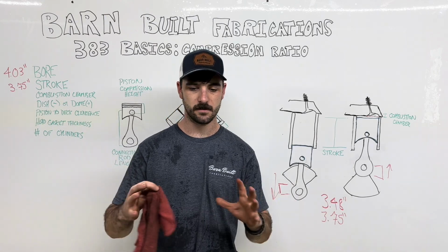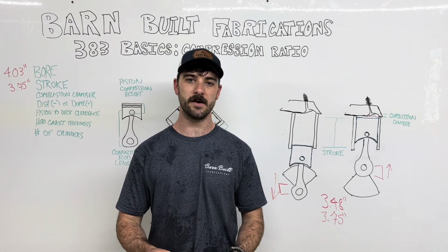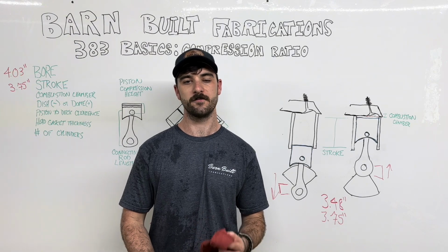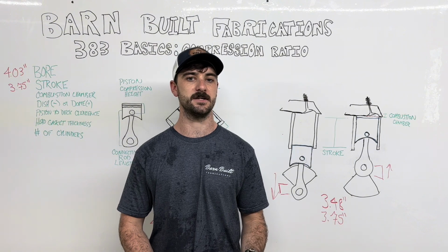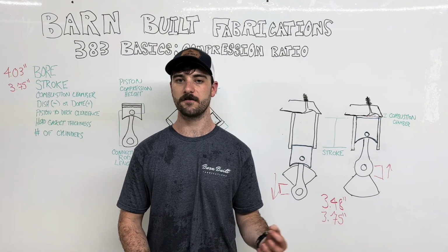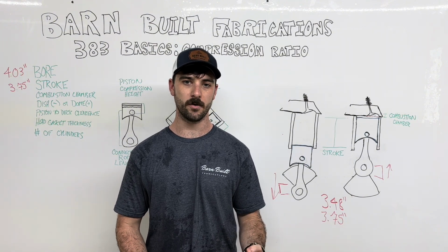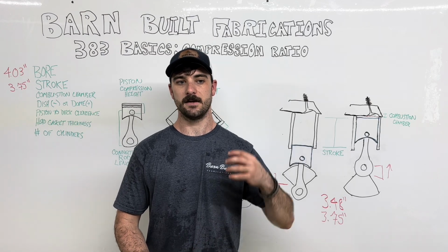But that's within parameters. There's a limit to that. Whenever your compression is too high for the fuel that you're running, you'll run into something called detonation. Detonation is the pre-ignition of your air-fuel mixture before its intended point, and it does it explosively.